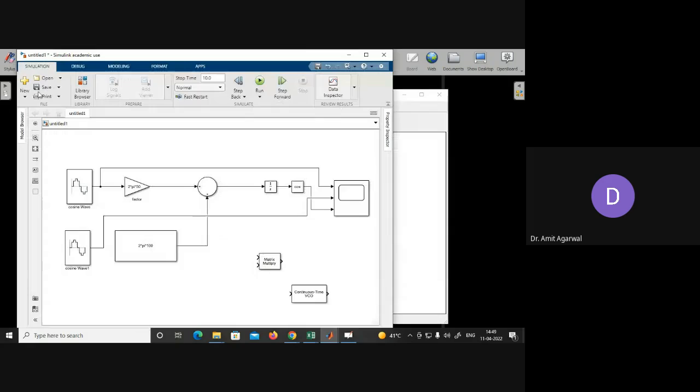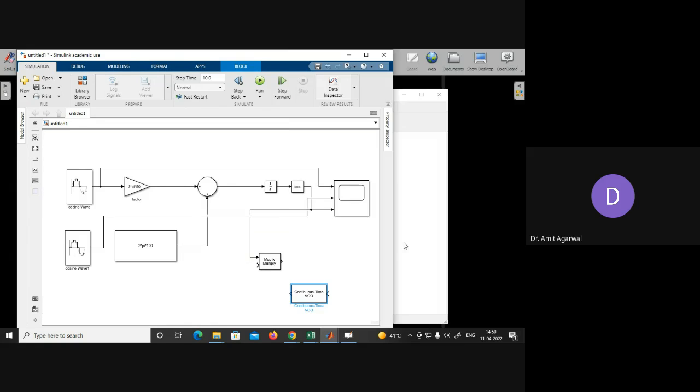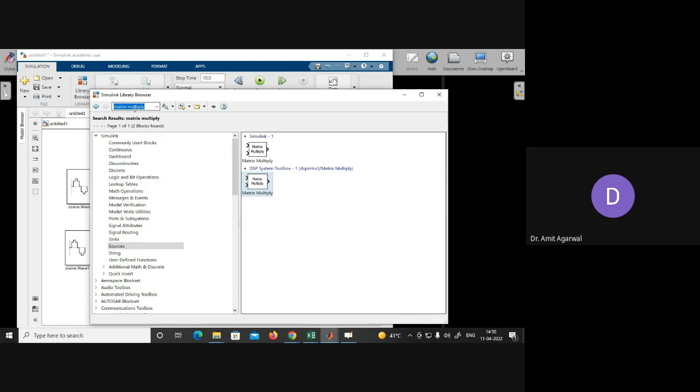This is frequency modulation, correct? So you have to connect this, and then this output we have to flip, right? Output of VCO, and now we have to take a low pass filter.